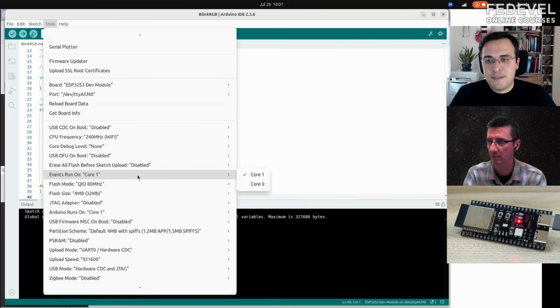Here it talks about the event queue. It is a programming concept in Wi-Fi and BLE applications. There is a Wi-Fi stack or BLE stack that runs on one processor. It's like a state machine, you can see it like that. Whenever the state of the stack changes, for example a new Bluetooth device is connected or Wi-Fi is connected to a hotspot, it signals an event, and then the event handler should run separately on a different core.